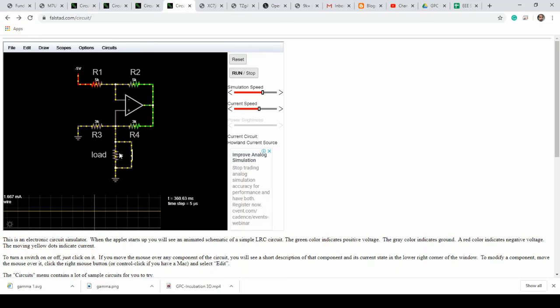1.667 milliamps. Look at it again. In this case, when the switch is open, 1.667 milliamps flowing through the resistor. Though it is 2 kilo ohms, now it's short circuited, it's still flowing at 1.667 milliamps. You can see that below. Though the voltage is 0 across the resistor, the current still is maintained through the switch.